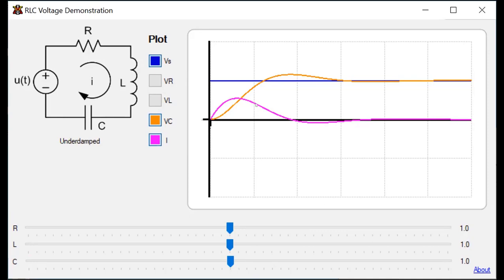Now, you might expect that the voltage across the resistor would never get to be above 1, like it did with the first order circuit. But what's different is that, remember, the inertia through the inductor doesn't like change. So it's going to continue to push current through that capacitor, into that capacitor, charging it up still more. And that capacitance will actually rise above 1 volt, more than it's even being charged to. Then it's going to start to reverse itself.